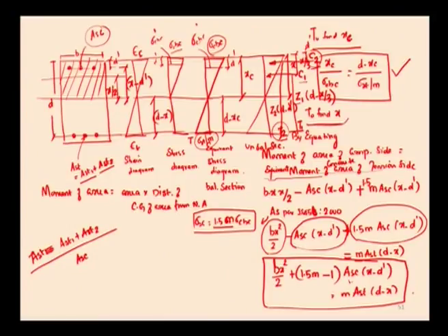Then to find out x, in the case of an unbalanced section, since the neutral axis is situated at the center of gravity of the section, we are going to equate the moment of area on the compression side to the equivalent moment of concrete area on the tension side. So, here b x square is the total concrete area above the neutral axis into the distance, that is, the area of the whole concrete into the distance of CG of area from the neutral axis.